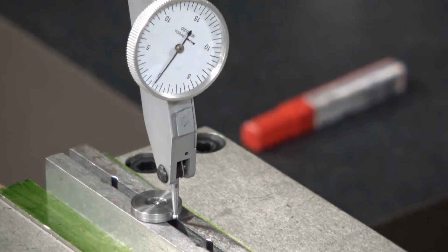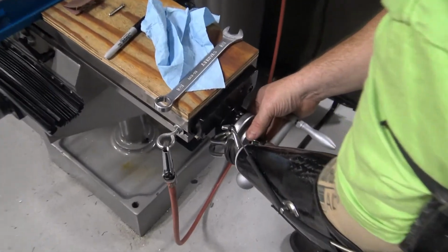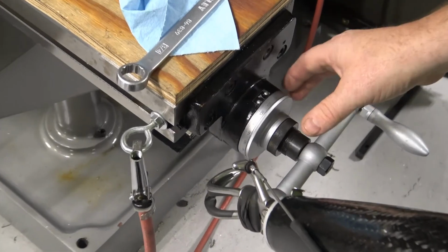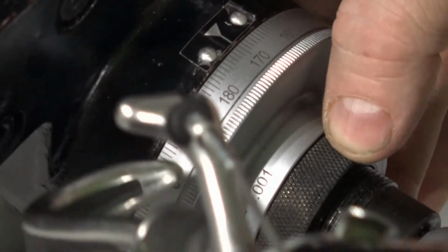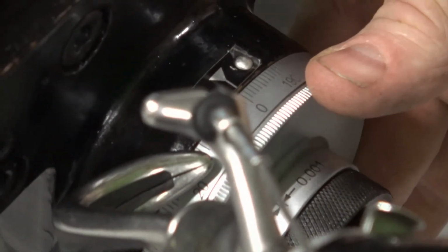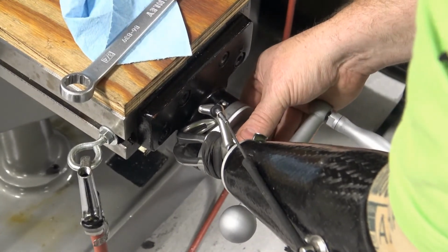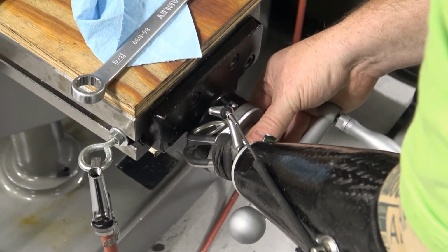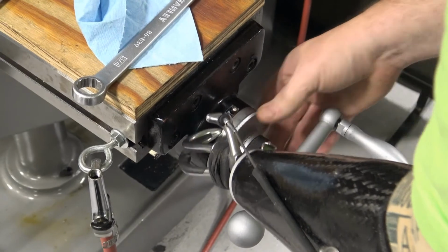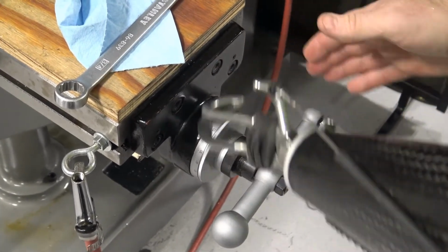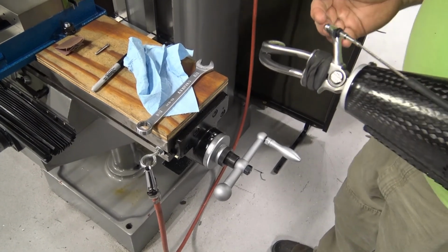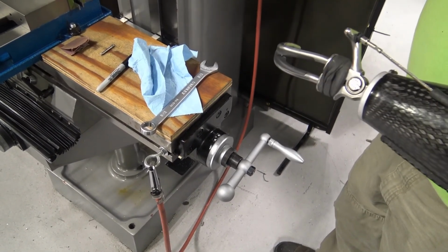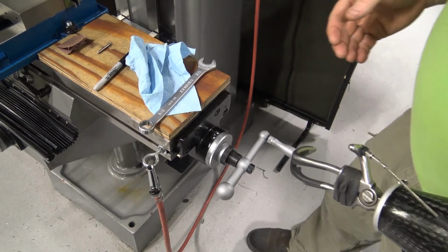So now that we've moved clockwise with this hand wheel, I'm going to unlock the hand wheel dial. Notice I'm not moving the hand dial. And I'm going to set my dial to 0. Okay? Now keep in mind that the last direction that I rotated this hand wheel was clockwise, so I'm going to continue going clockwise so I don't interrupt or add backlash into it.